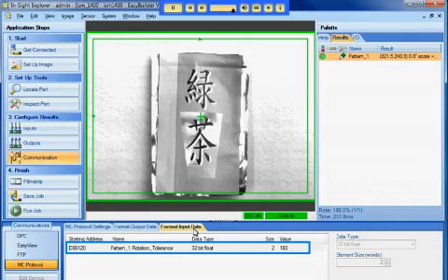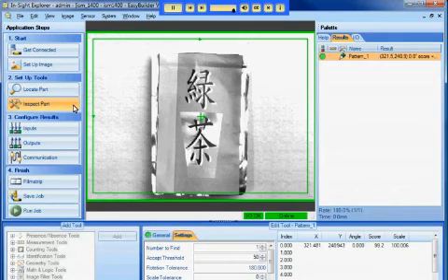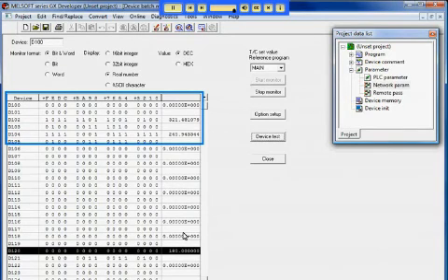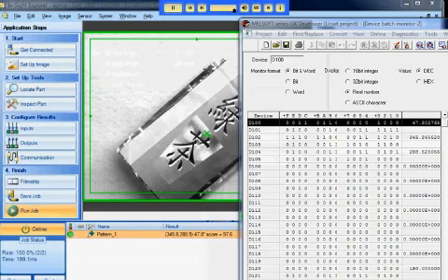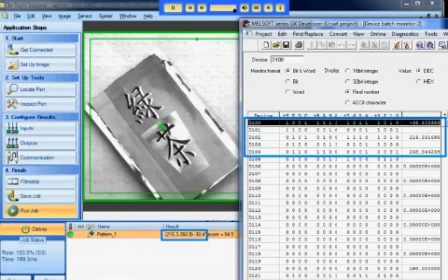Looking at the Format Input Data tab, I can see Insight has read the new value of 180. The rotation tolerance of PatMax has been updated to plus or minus 180 degrees. With GX Developer, I can see that the PLC has read the PatMax angle, X, and Y values from Insight. As I trigger Insight, I can look at the results in EasyBuilder and GX Developer Update with each inspection.